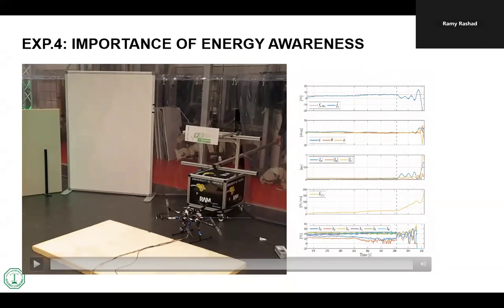So I'm trying to push further. I'm telling it to push harder, and there's nothing to push at. So what happens? It keeps on increasing the stiffness. It feels that I'm not pushing strong enough, so it needs to increase the stiffness, and make it harder and harder and harder until you hit what? The limit of the actuator, and then you just become unstable. So this is a typical example of what the loss of passivity means.